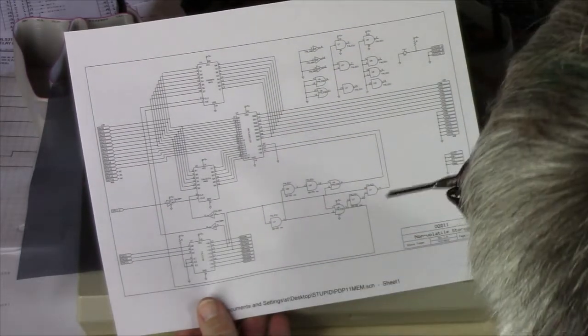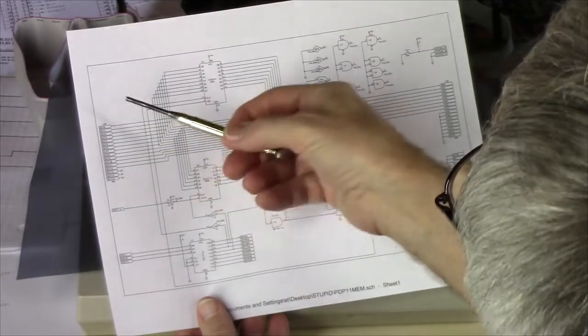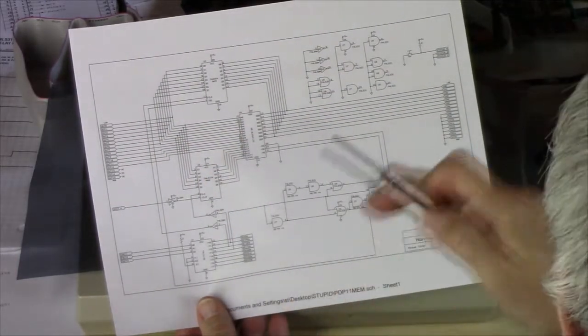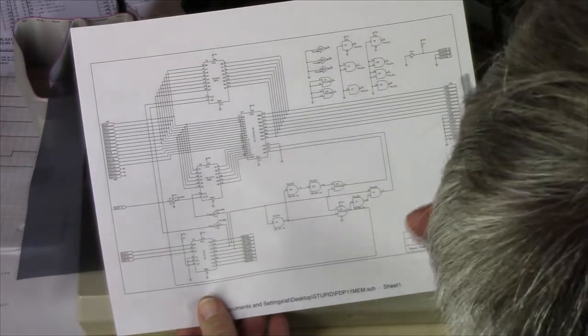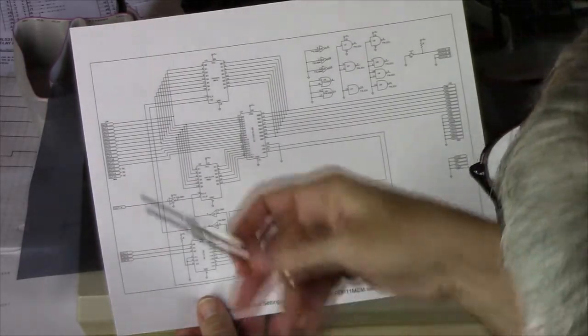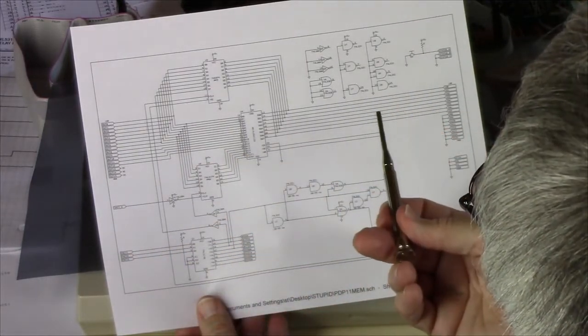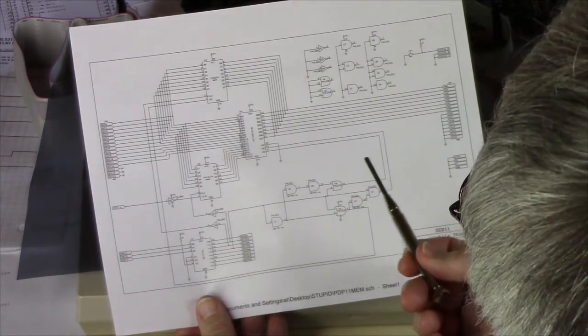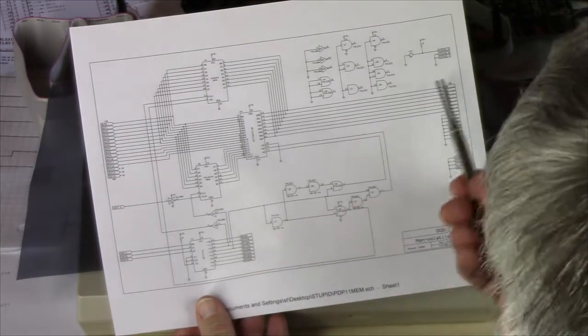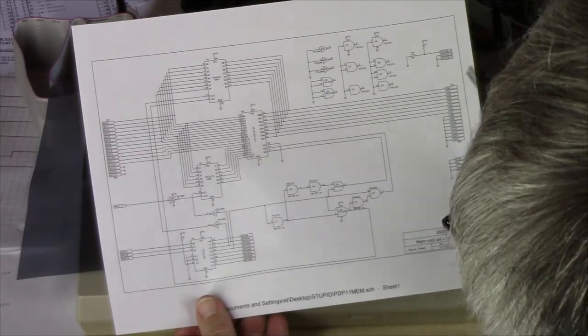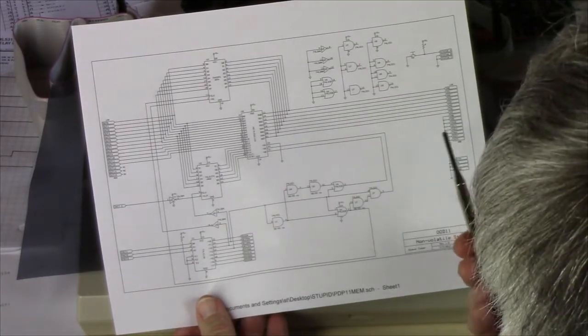Reading just involves setting the page register first. But that's something you're going to do once if you stay within a page. You set the page register. Then you set into the data register the address within that page, a 13-bit address, and then you can just read the data out of the data register, and that's a read.